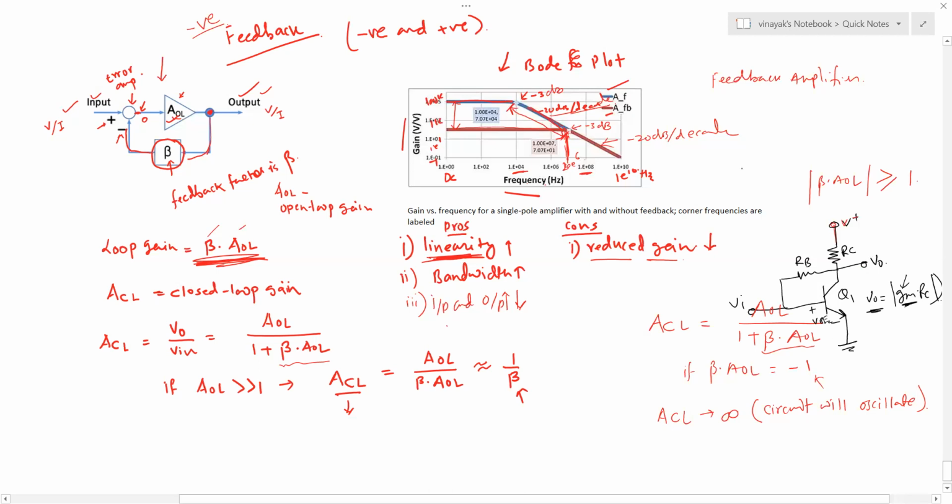So what you do here, you improve the circuit by placing an emitter degeneration resistor. So it is RE, and then again you have the same condition of setting the bias point of the transistor, which is, let's say, RB. Again, you maintain the VBE here and the output you take here, and then you have this RE, and then there is a voltage drop across it, VE.